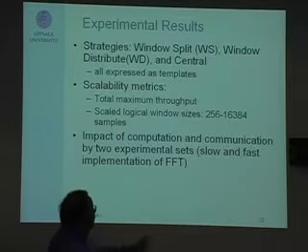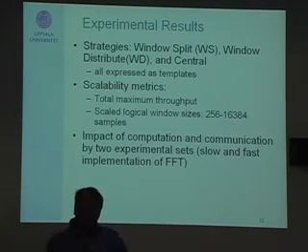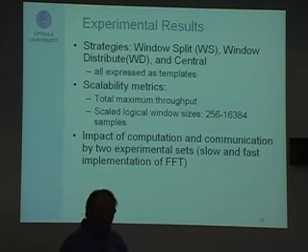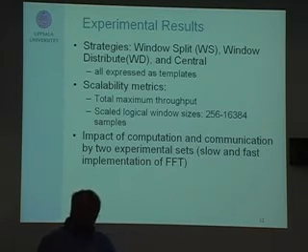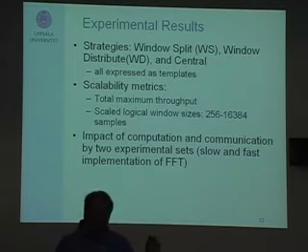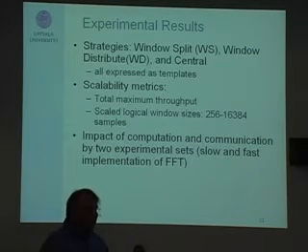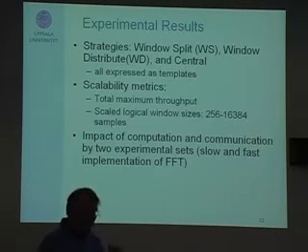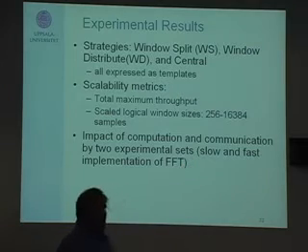And what the astronomers want to do is not use only 256 size. Remember, when they have a raw signal, they do a Fourier transform because they want a frequency spectrum. Then you want to tune in the frequencies you're going to look at. The bigger window you have, the more you can tune, the more information you retain, and the less information you lose. So what we would like to do is to scale the window size, and we scale it quite a lot, to 16K there.